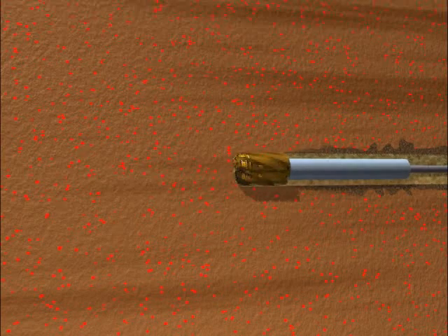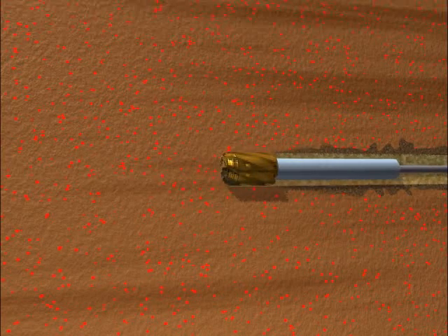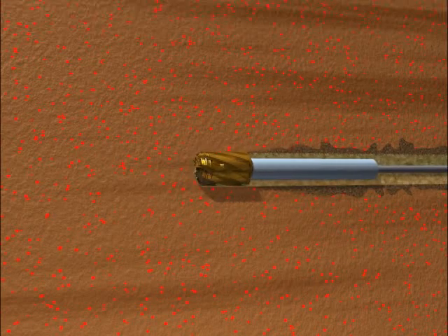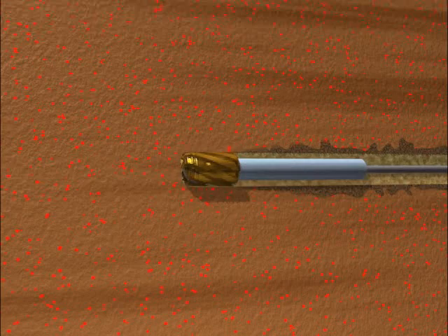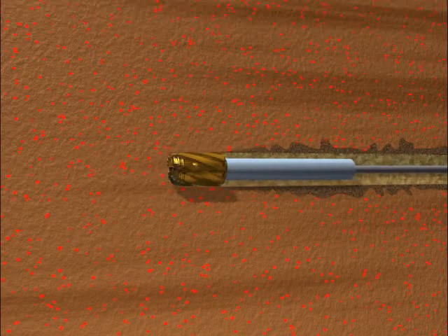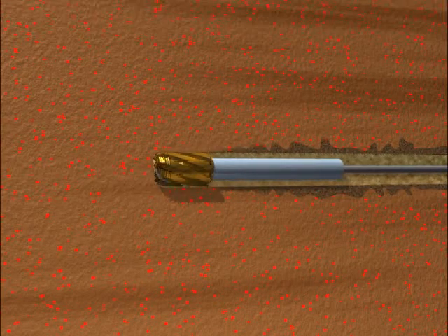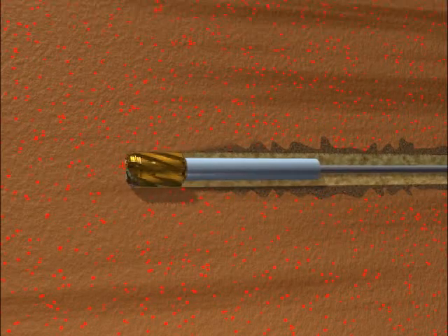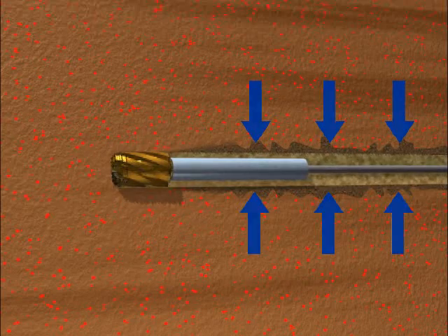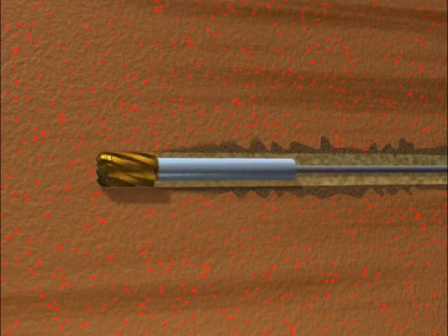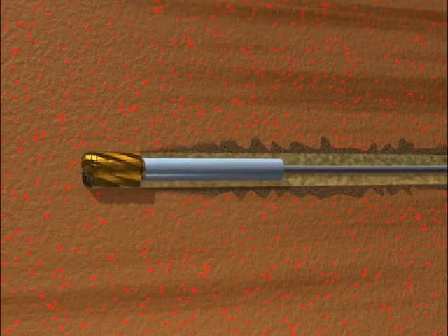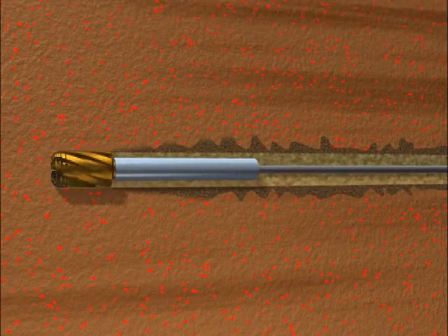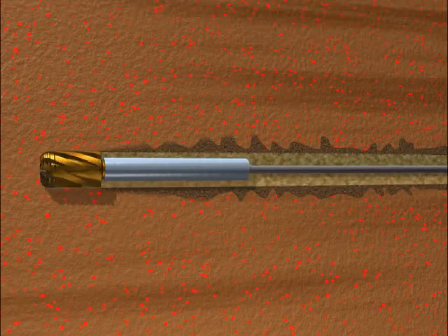In conventional overbalanced drilling operations, the hydrostatic pressure exerted by the drilling fluid in the well is designed to exceed the pressure of the hydrocarbon fluids in the reservoir. Since the pressure in the hole is higher than the pressure in the rock, fluid and fines are lost to the formation. These losses cause damage to the near wellbore area, resulting in reduced production. Experience shows that even a short exposure to overbalanced conditions can severely impair the productivity of a well.